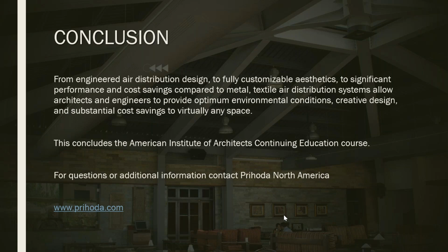Right. So again, I just want to reiterate, Nathan, that we design standard at a 1/2-inch static pressure, and let's say you have an engineer who would like to design it at 1 inch. They're saying there's 1 inch at the inlet. We can do that. You just have to let us know, because if you don't let us know what's at the inlet, we're going to design at the standard of 1/2 inch. Then the issue comes in if you're actually putting 1 inch at the inlet. In that case, you can turn your unit down to where there is 1/2 inch at the inlet, and then the fabric duct can work the way that it was designed. Very good.